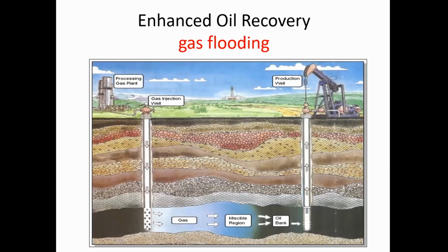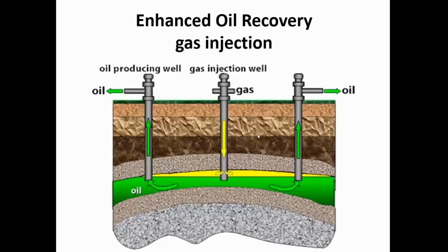I'm sure you will answer me. Horizontal. Very good. So that's horizontal flow. But if I am injecting this yellow gas in that yellow area, what do I prefer here? Shall I prefer vertical permeability or horizontal permeability? Vertical. That's the difference, and that's what I mean by vertical flow and horizontal flow.